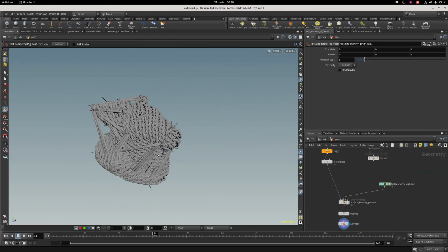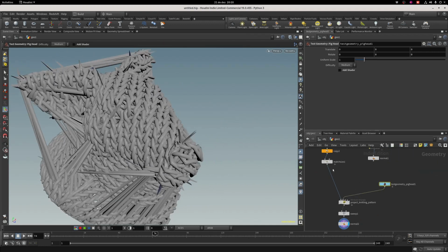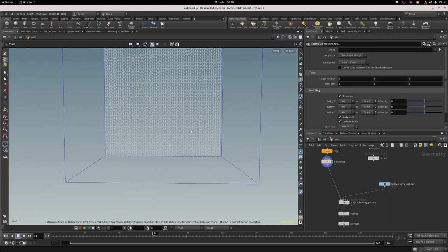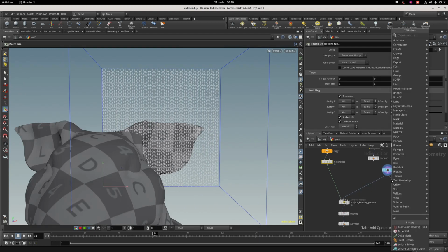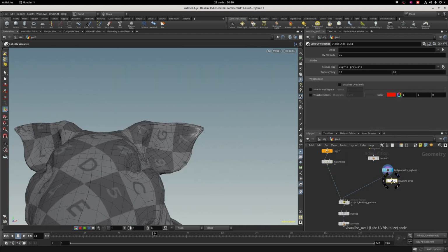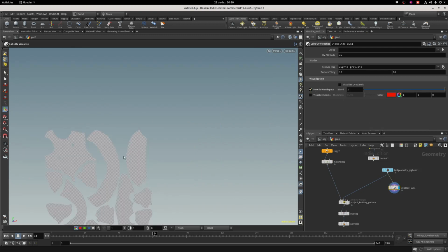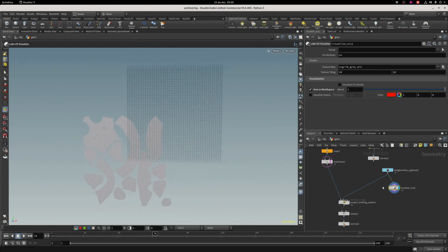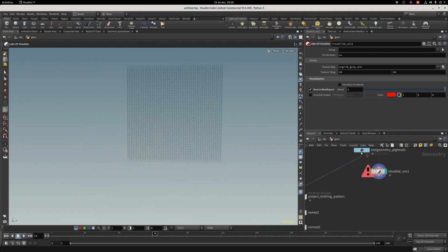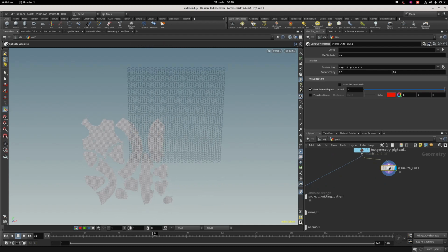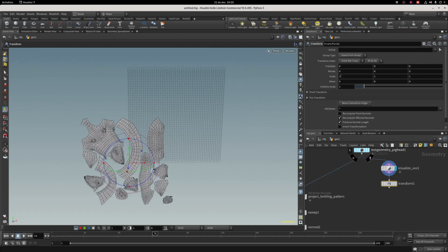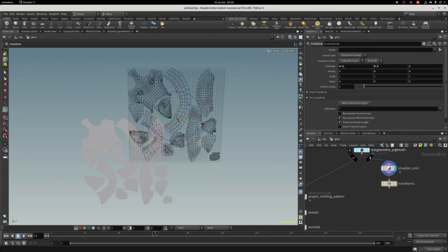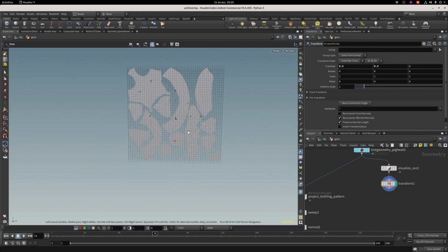The reason why we're getting these spikes is because we have a flattened pattern, and we have these UVs. Let's visualize that. So UV visualize can allow you to view in world space. So yeah, that's what you have. This is visualizing to the centered world origin, but instead I want to view at the 0 to 1 range. So I'm going to transform 0.5 units in both x and y axis. Now we can see both overlaid.